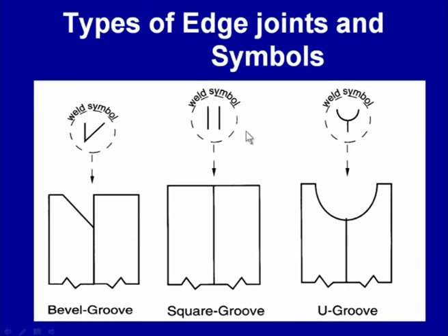And for developing the edge joint using the U groove geometry helps in developing a very strong and sound weld joint, because it facilitates proper melting and the fusion of the components to be joined.